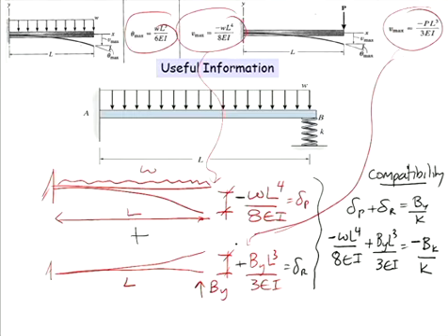If we're getting a Z value for the secondary beams that's much smaller than what's on the table, do we use this? Yeah, that's all you can do. You go into your shop and say, I need something really small. The lowest size in the table is only like 200 to 300, so that's the size here. If this was a real job, you'd try to find a small beam that's not a UB, maybe a square hollow section. But you're limited to UBs.